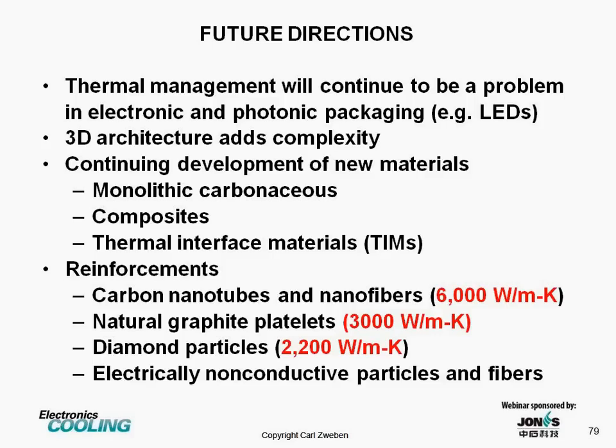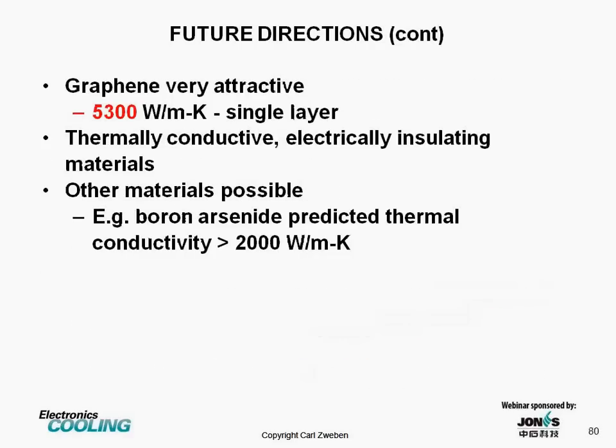Natural graphite platelets, we've seen, are already being used. They have thermal conductivities as high as 3,000 watts per meter Kelvin. Diamond particles, again, are in use, 2,200 watts per meter Kelvin. And I anticipate the development of electrically non-conductive particles and fibers. Of course, diamond particles are electrically non-conductive.